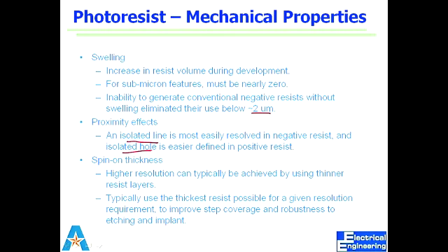In etching, you might have the etchant seep through and attack the underlying layer, which is supposed to be protected. So we use the maximum thickness that we can for that particular process, just to cover the steps uniformly.